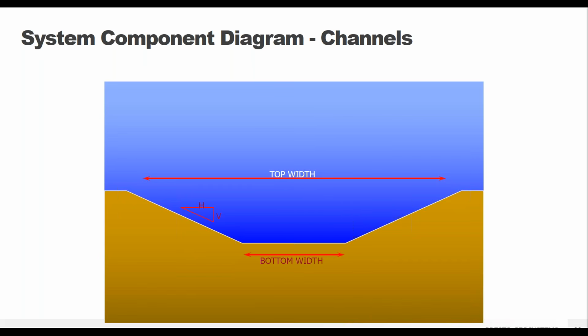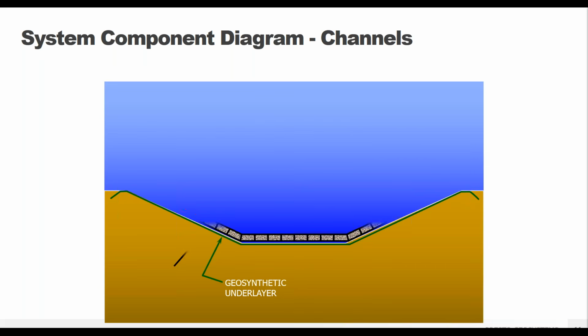So the process of building up a channel protection system goes something like this. To begin, we have our channel, with some pretty standard dimensions. We've got our side slopes. Then, depending on what infill material you choose, a geotextile separation layer may or may not be required, so you would put that down directly on your channel. And then you're going to put the GEOWEB panels in place. Note how the panels typically have some sort of crest anchorage at the top of one or both side slopes. This is important both for anchorage and to prevent water from flowing underneath the panels, which could potentially cause undermining.